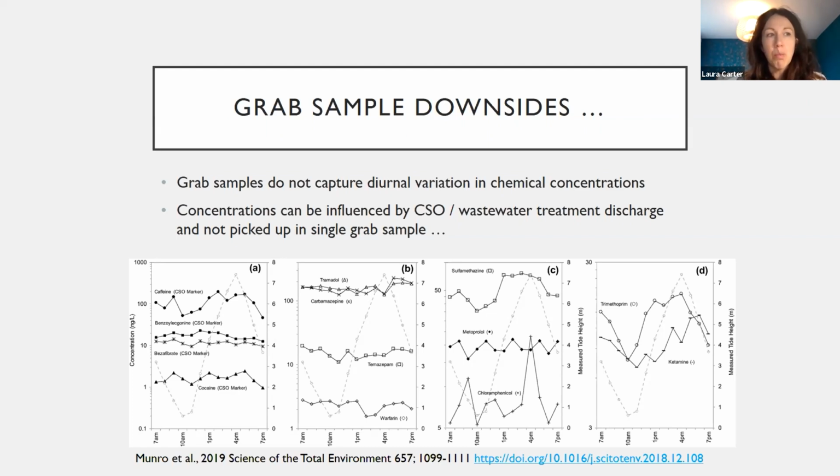What we know about the Thames is that the water levels change on a daily basis and can be up to about 7 meters. This typically occurs twice a day. And the river flow is actually relatively small compared with the volume and the tide. So on the plus side, it is relatively well mixed. So coming back to this figure, the black data points represent the mean of 2 grab samples that were collected, and the grey dashed line is the tide height at the time of sampling.